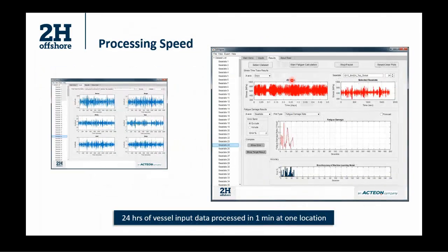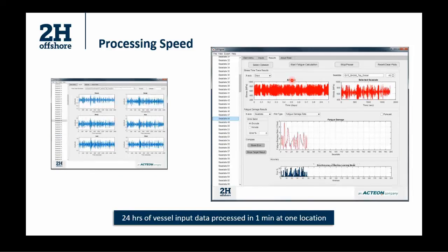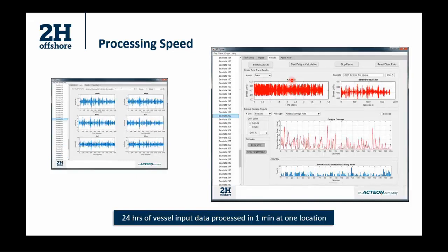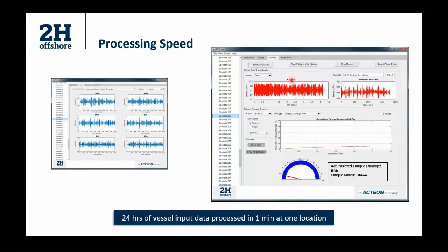That basically shows what happened in the two case studies, and we have demonstrated the level of efficacy of the machine learning model. Once this trained algorithm is available, we can process 1 day of data within 1 minute. This allows for deployment on edge-based or cloud-based infrastructure, providing near real-time response. We can obtain real-time stress, load, and fatigue trackers, obtain accumulated fatigue damage, and remnant fatigue life info.